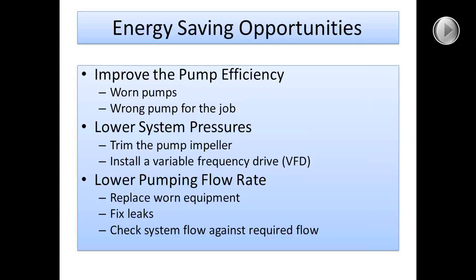Another good opportunity to save energy is if the system's operating at higher pressures than it needs. I just mentioned replacing hand lines and wheel lines with center pivots. Typically, your operating pressures are a lot higher with hand line and wheel line systems. They need higher pressures to operate well than you need with center pivots. And so your flow rates may match up, but you're running at a lot higher pressure than you need, so there can be good energy savings opportunities there.